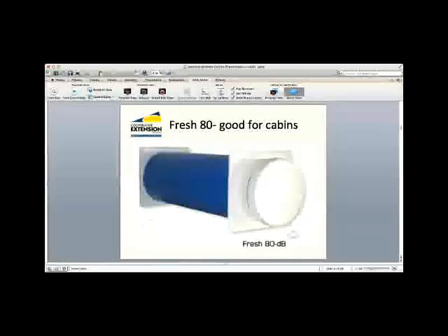And then on the inside portion, you kind of cap it off with that mushroom-looking head and that square plastic piece. Slip that on the inside of the wall, so that the tube is basically going through your wall. And the idea is that by pulling on that drawstring, you allow fresh air to come into the house, because that drawstring activates that spring-loaded mushroom-looking head, and it allows a small crack that you can see to the left of it for fresh air to come in.